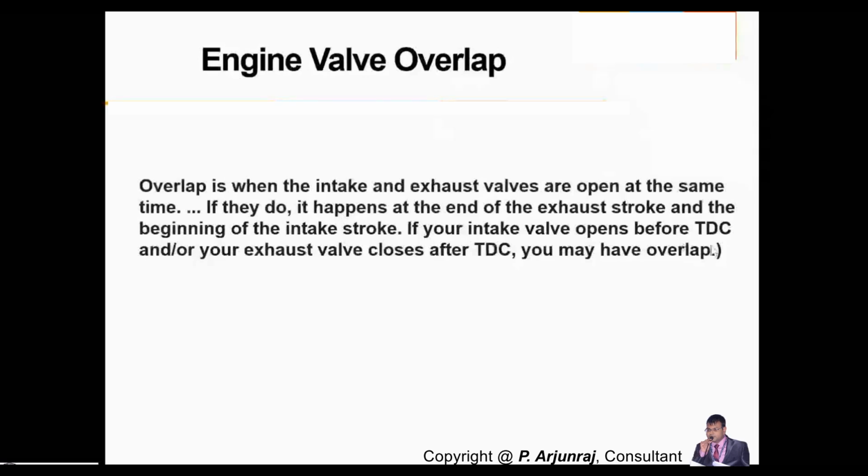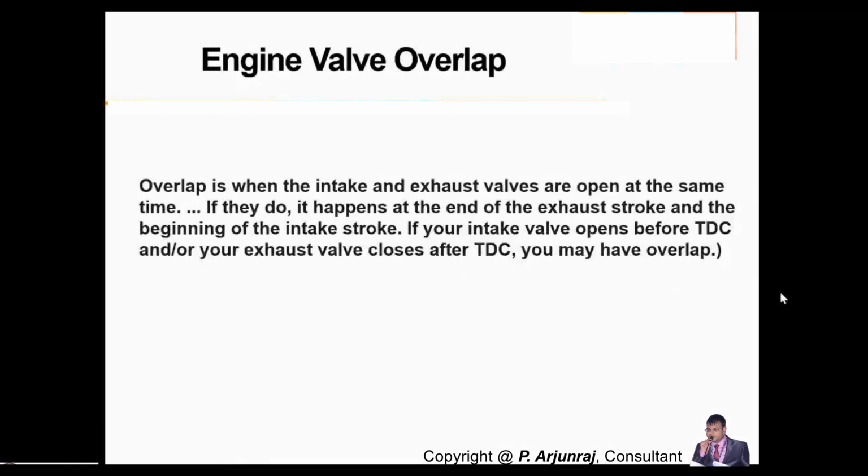So if your intake valve opens before top dead center and your exhaust valve closes after TDC, you may have the overlap. But you should not define it such a way that the period of valve opening condition between intake to the top exhaust is called overlap.